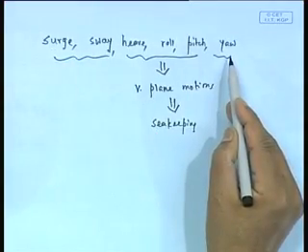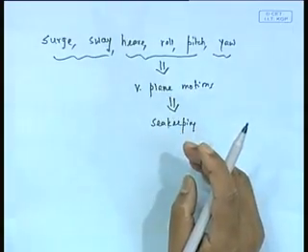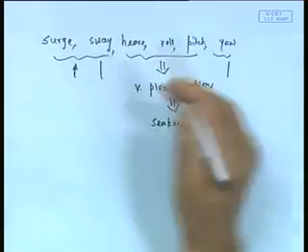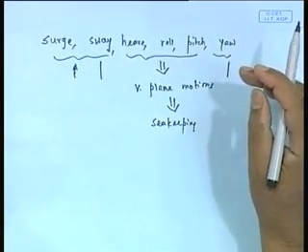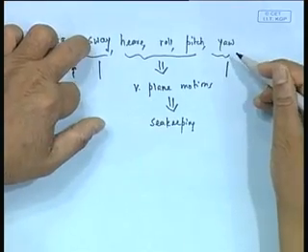Of course, there is a big difference. Not that I don't have surge, sway and yaw in seakeeping. I do have, because in seakeeping I had existing waves in water. But in maneuvering I don't have existing waves, and I am looking at sway and yaw primarily, not even surge. The reason is that in calm water surge is nothing but forward motion, so it is a resistance problem. So in calm water, sway and yaw is what we are talking of in maneuvering.